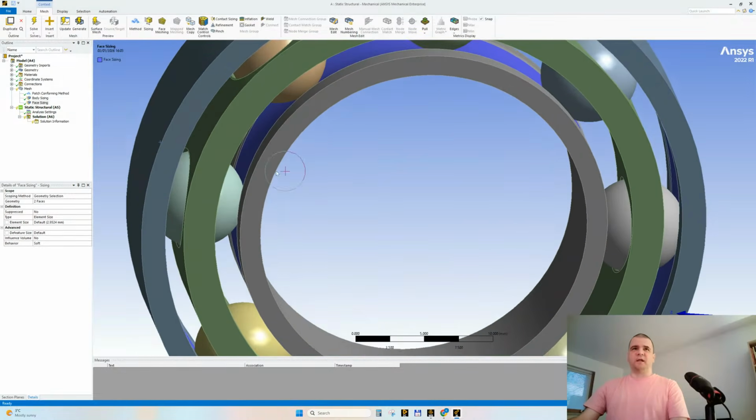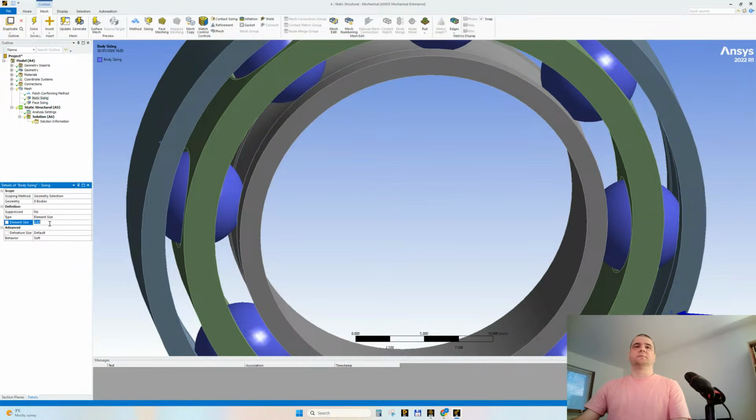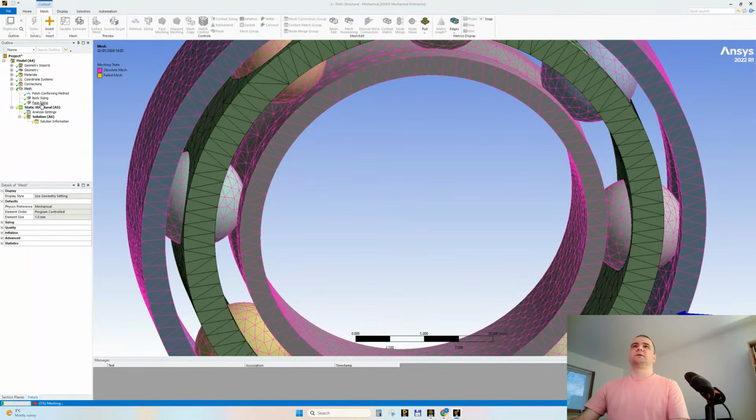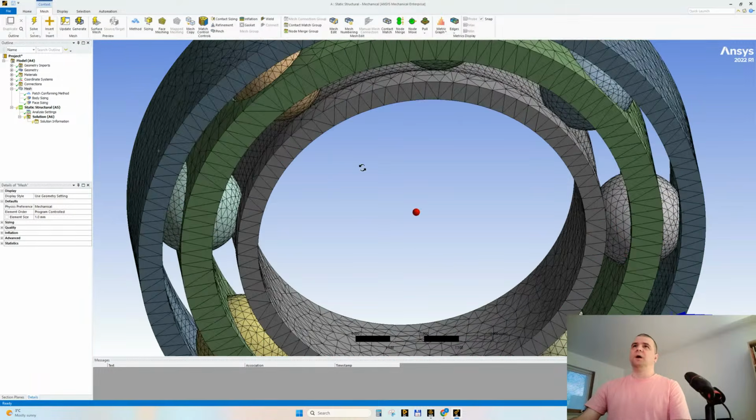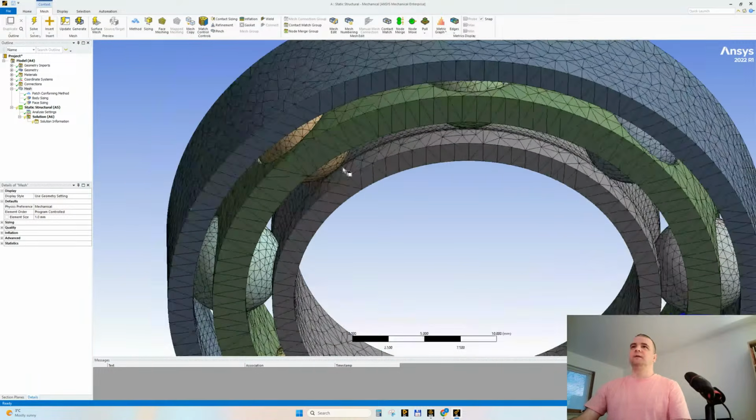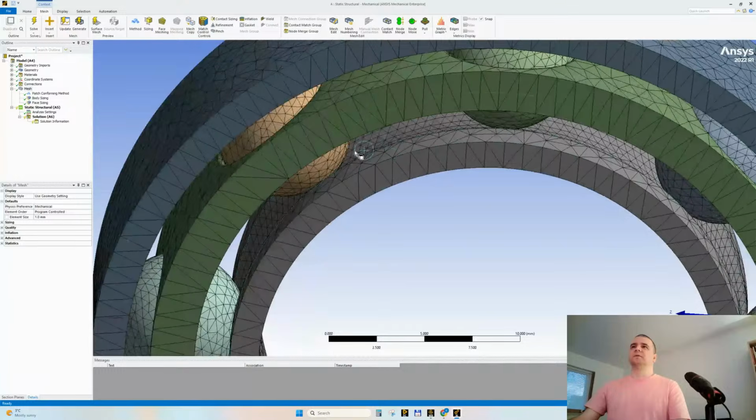The groove mesh density, all right? So here, let's make it 0.555, and also for the body, 0.555, all right? Right-click, generate mesh. It's a guesstimation, it's from an airplane view, but you see that it begins to look very professional.